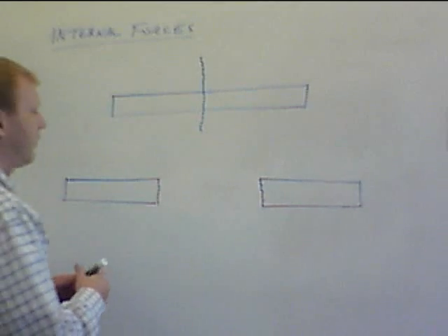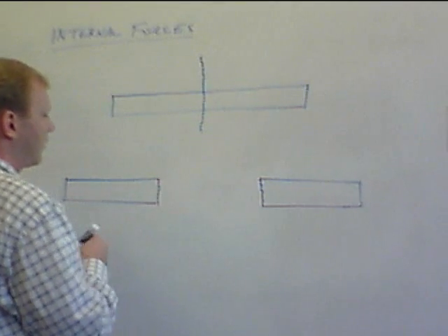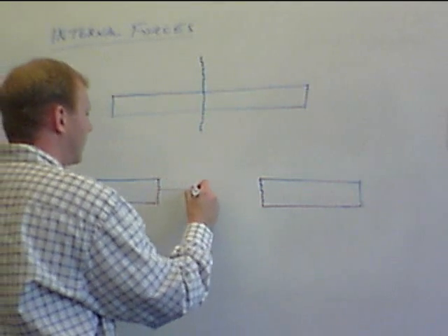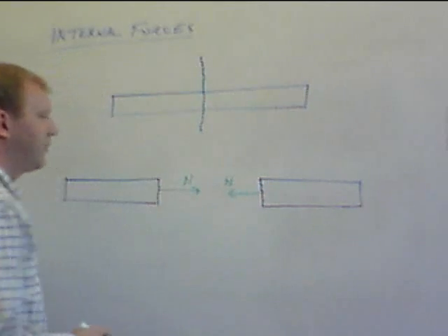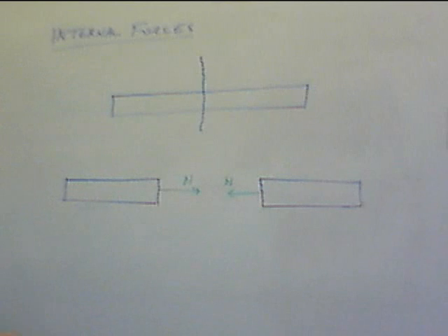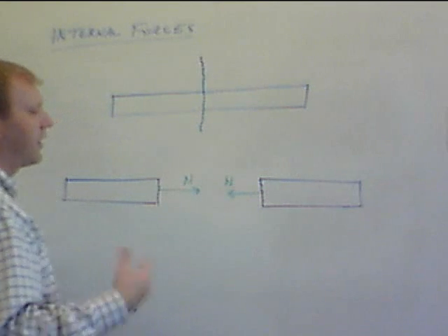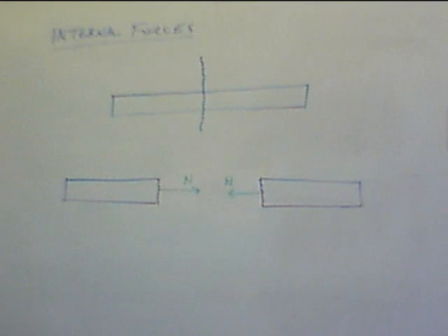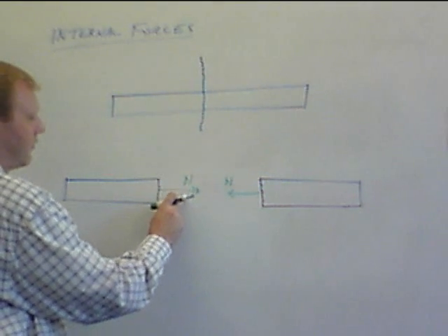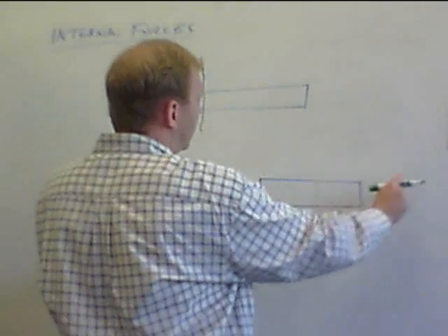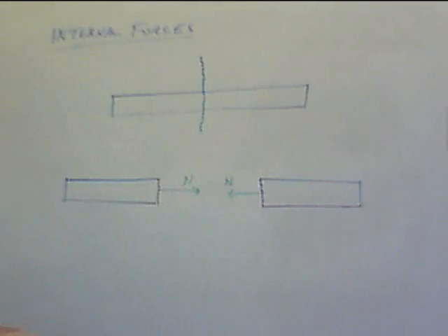We can have a tension or compression force. That's what's called the normal stress. And it's going to act on both, again, opposite directions, both ways. Sign conventions here are going to be a little confusing at times, but typically we draw that this beam being in tension is going to be the positive normal force. So again here, tension is going to be the normal force on both pieces.